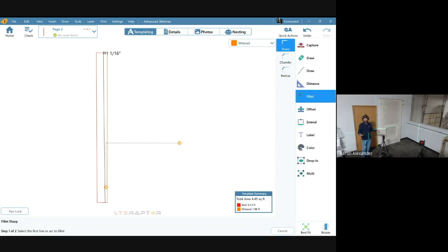You just do your homework, check out the price points, and check out what the accuracy is. Usually the price directly affects the accuracy of that thing, right? The one I'm using right here, the Leica Lino, it's 0.2 millimeters per meter. So it's extremely accurate, okay?